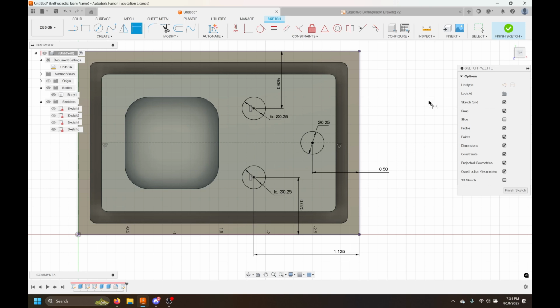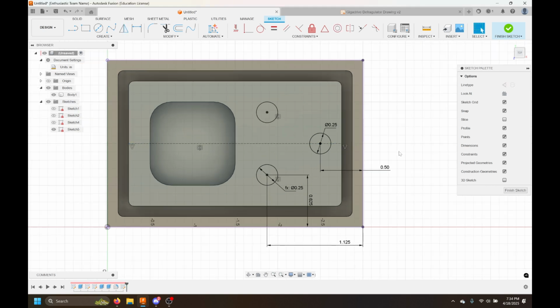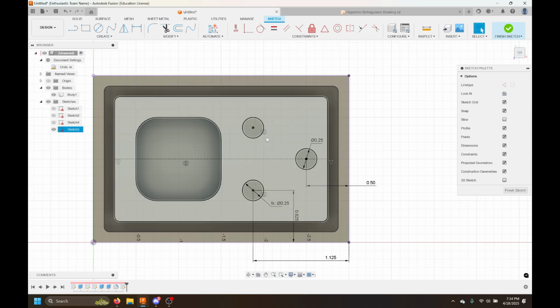That's easy enough. The other way is if I just make this bottom circle. So I have this circle and this circle here. I can use the mirror tool. I grab my object, and then I select the mirror line, another box over here. I'm going to grab this middle line because we already put it down. It's the line I want to go around, and it'll put a circle down there. Hit OK. So that's the other way you could do that.